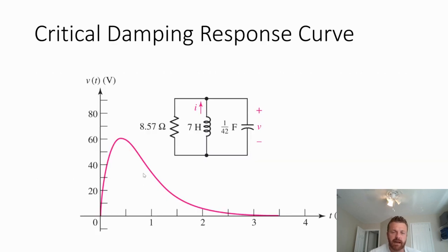But the one thing I wanted to bring up for now is that if, for example, I took this figure from the text, with that value of R, L, and C, and you notice how precise the resistor value has to be, imagine being able to even achieve that in practice. What you find is that the actual response of the voltage still has that same general form that we've seen previously, namely it increases rapidly from that initial condition until the asymptotic behavior of the decaying exponential starts to dominate and it converges towards zero.